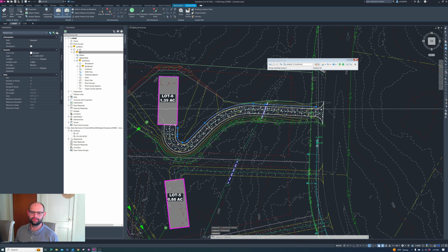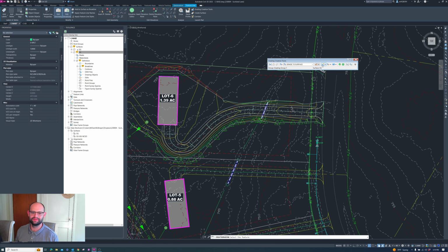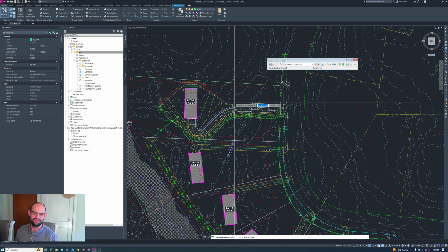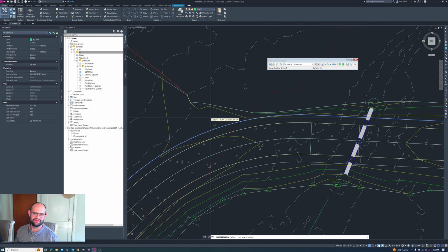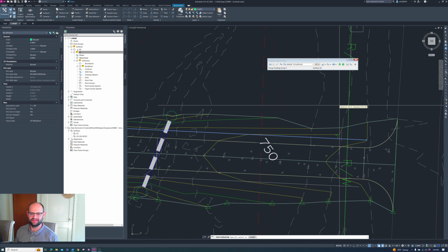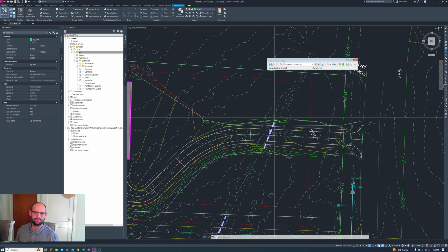We want to set a grading group from this shoulder now. So I'll create another one. Select the grading side to that side. Don't want to do the entire length, so I'm going to hit no. See this little arrow down here? We want to start somewhere in here. Accept that station, work back this way, there. And AutoCAD is generating that grading group now. There it is.